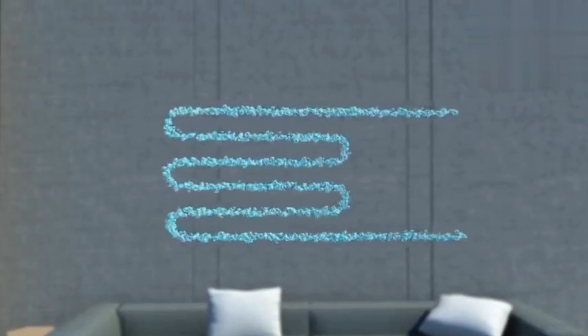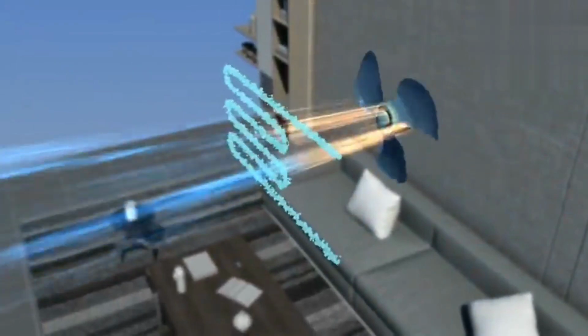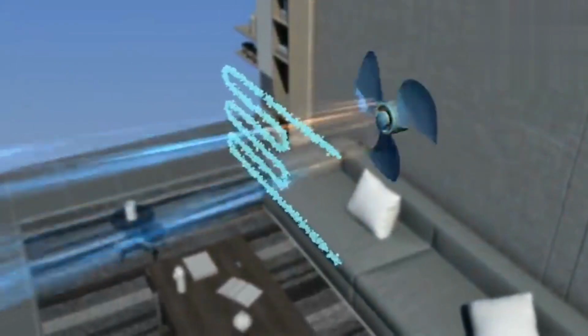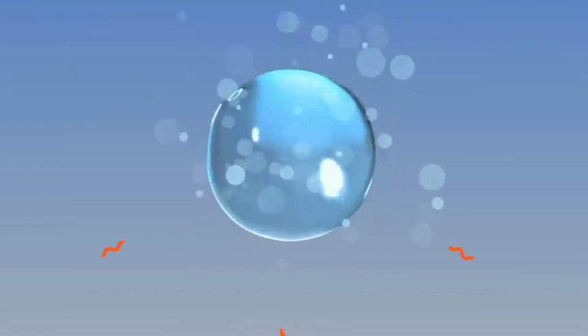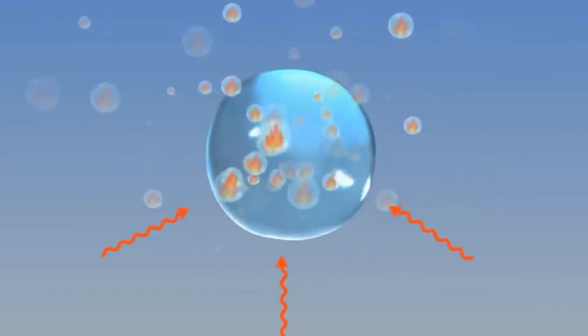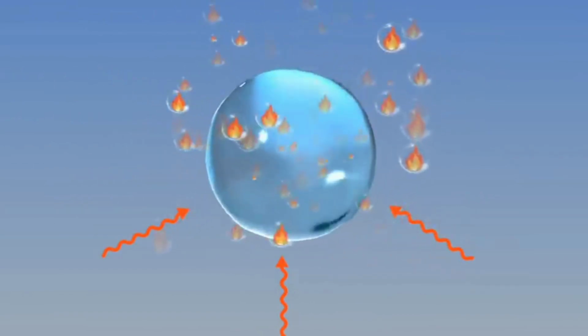When we blow wind from behind the refrigerant, air that lost heat becomes cooler and a cool breeze comes out from the front. The refrigerant used in an air conditioner tends to evaporate easily and has a high latent heat of vaporization, which makes it perfect for a cooling device.